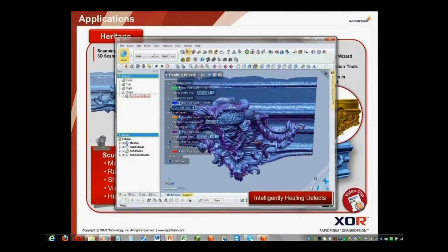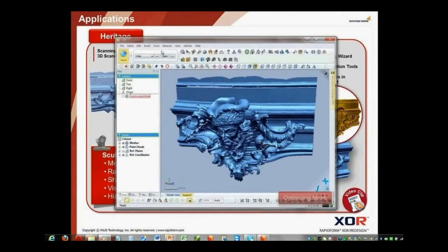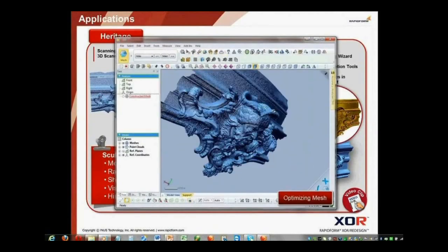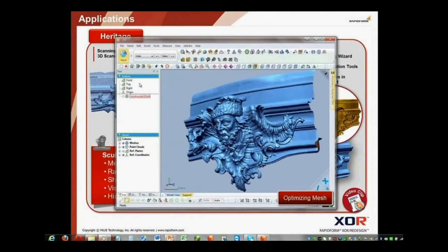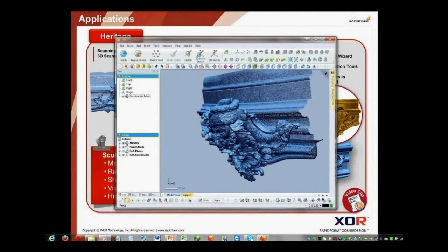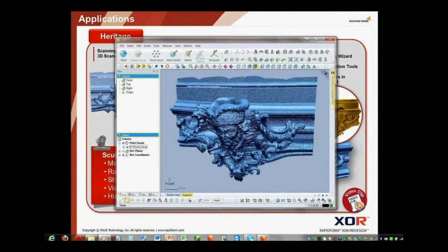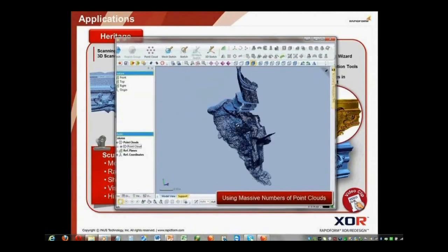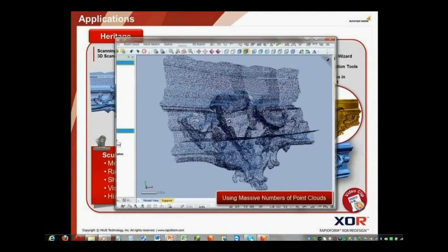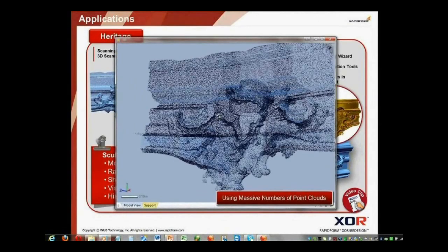In this case, we are doing a little bit of mesh handling, mesh healing, for example, to correct some mesh errors. Then we have the remeshing tools like rewrapping, and then you can see also if we have mesh with holes or mesh with defects, then we can also create a very nice looking mesh.